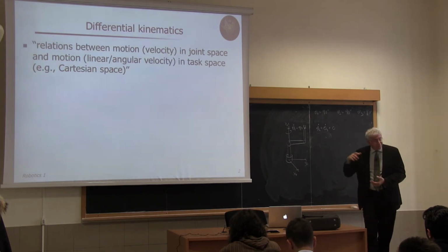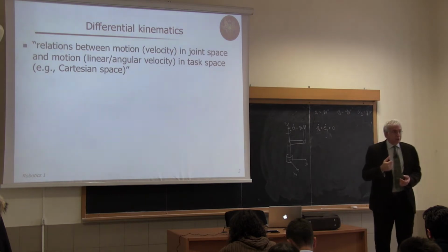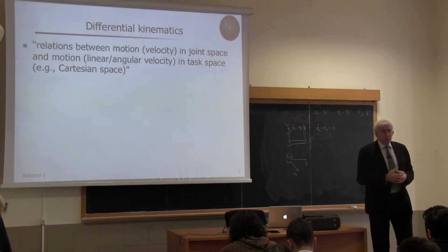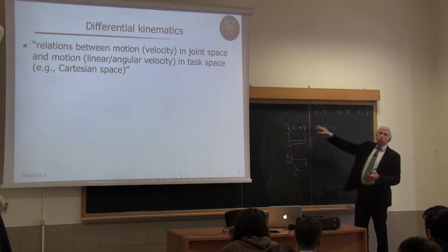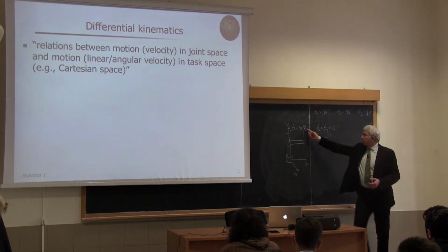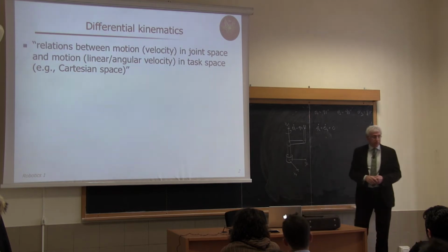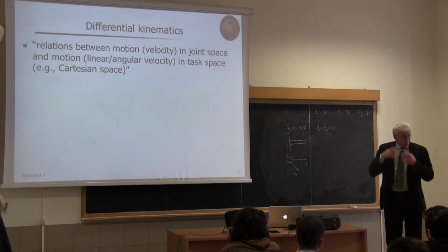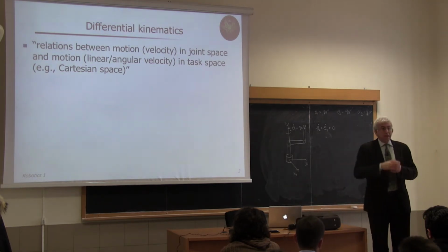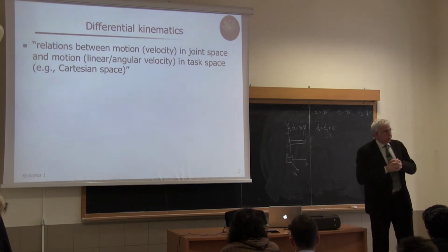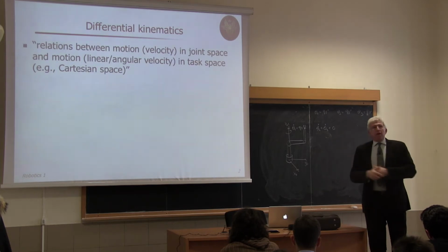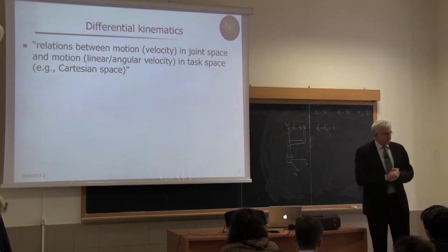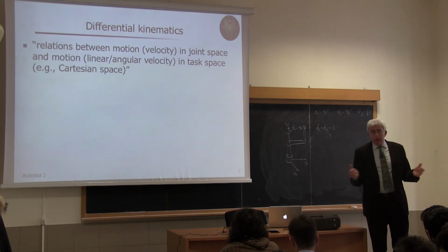And here it is more or less the same, because the inverse differential problem is, okay, suppose that I have the robot in some configuration and I want to have a velocity, say, coming out of the blackboard. Linear velocity and zero angular velocity, let's say. So what kind of motion should I impose on the joints so as to realize this? So it's a synthesis problem as well.